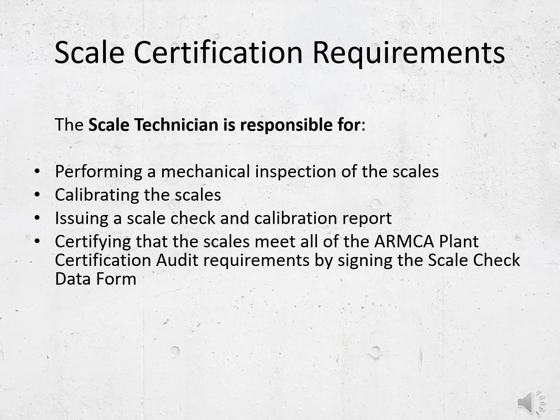The scale technician is responsible for performing a mechanical inspection of the scales, calibrating the scales, issuing a scale check and calibration report, and certifying that the scales meet all of the ARMCA plant certification audit requirements by signing the scale check data form. The technician's check and calibration report should show in detail the loads applied to the scales, the results observed, the adjustment made, and the recheck process to confirm the calibration action corrected the observed deficiency. As mentioned before, the serial numbers of the weight used in this process shall be recorded on the report for traceability purposes.